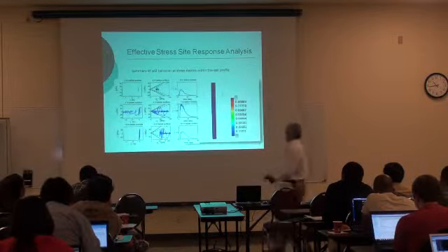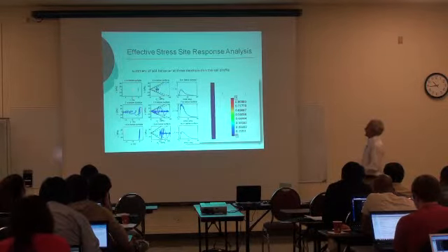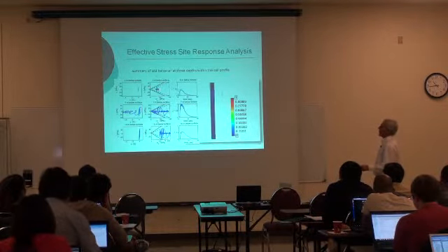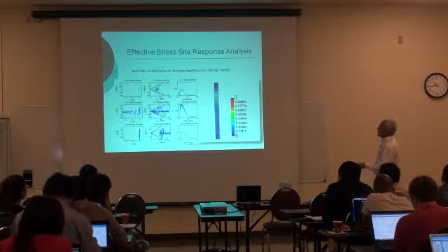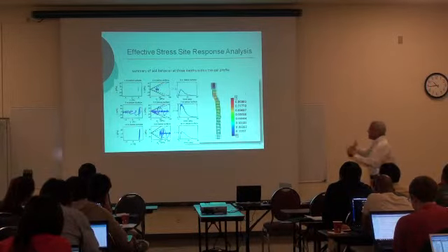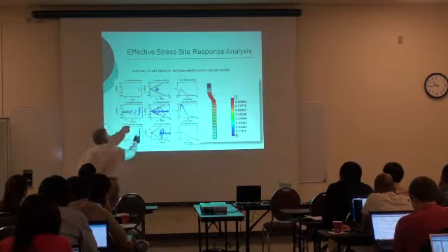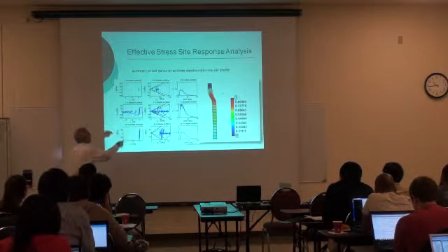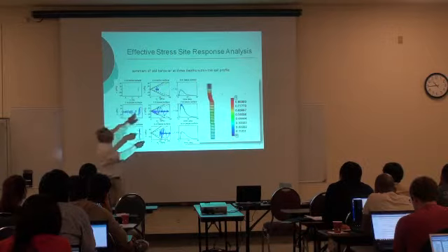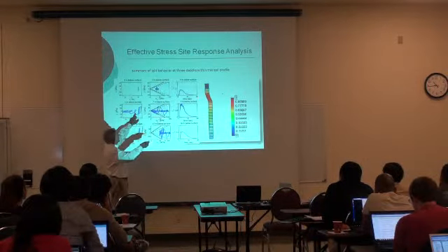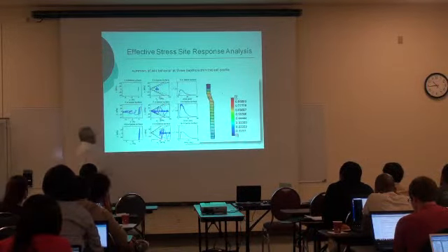And again, what you have here is the stress strain, the stress path, and the pore water pressure at 3 different locations. So you see the complex behavior, this is stress strain. At the surface, it's almost linear elastic. But look what happens when you are in the middle of the liquefiable layer, which is this. It's very, very nonlinear.